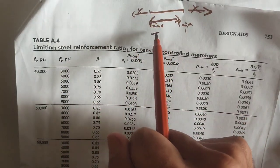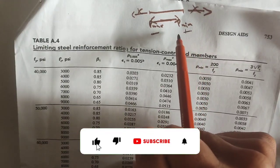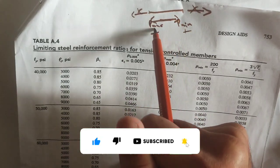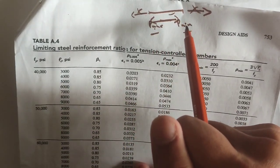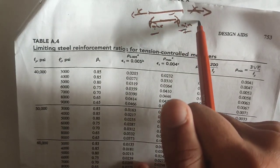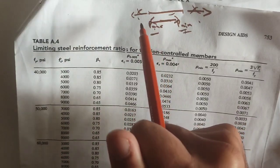This is rho maximum, the maximum reinforcement ratio, and this is the minimum reinforcement ratio. What you will provide is between this and this. These two are also included in this limit. You will not cross these limits. For example, you will not provide less than the minimum reinforcement in your beam and you will not provide more than the maximum reinforcement in your beam.